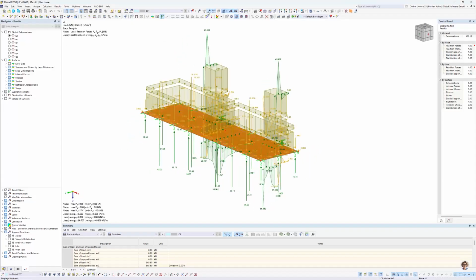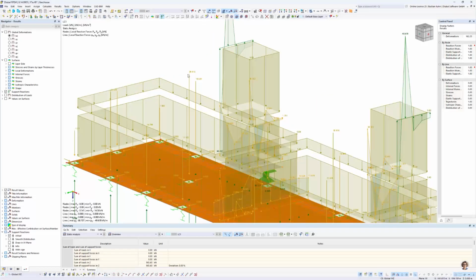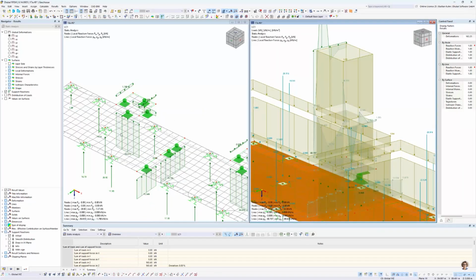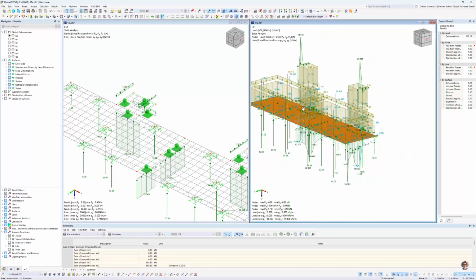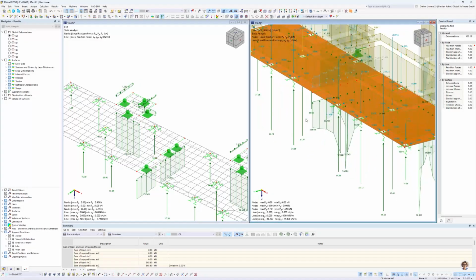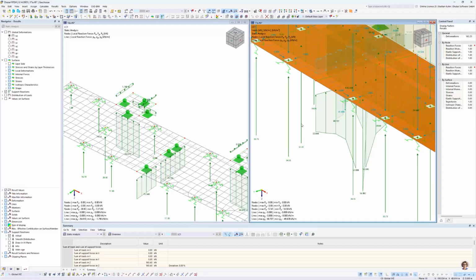And when we look at the forces, you have here the 28.9, which is, maybe when we tile it in this way, you see here 28.9. So it's taking the force from this node and applying it on this. And then, of course, together with the other load that I have in here, it's giving me this 57, which is also the normal force. So that's a way to regard 3D effects in 2D.